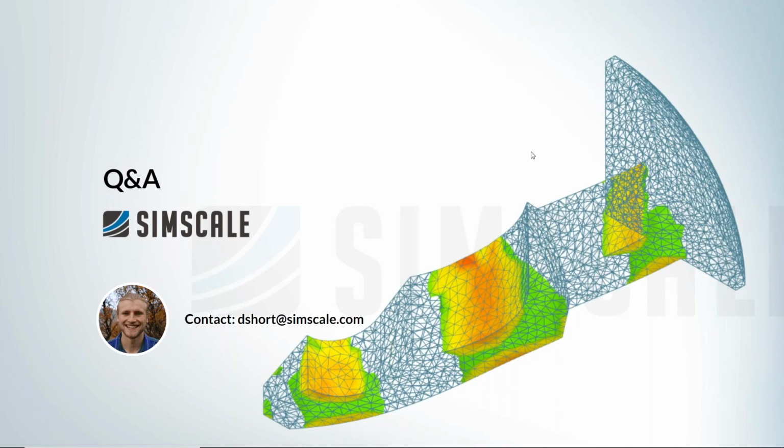That will be left in the hands of the designer. So when we see larger areas of stress concentration, it's going to need a little bit of design engineering expertise to say, that's the area where I need to apply a fillet. How could we change the kinematic behavior using either adding mass or taking mass away, so weight reduction, which is also obviously a design consideration for these types of products.